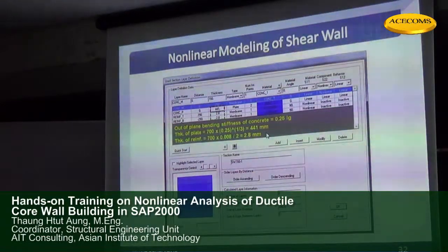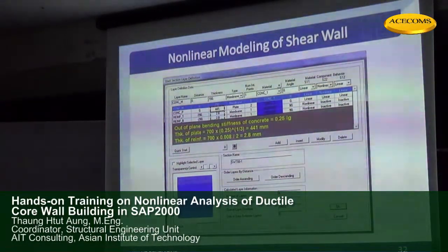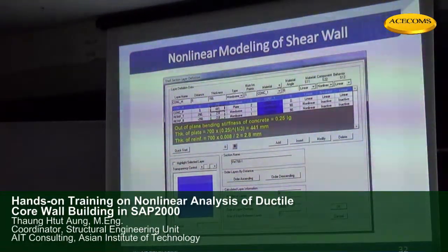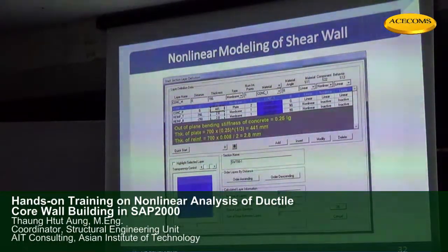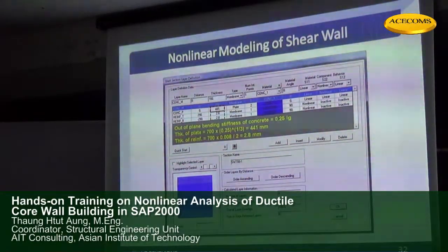Normally, when we do performance-based design, for the code-based design we use ETABS because this is linear analysis. And then we use the same model from ETABS. We just modify the stiffness modifier for service level evaluation for response spectrum analysis, and we check the service level in ETABS as well.